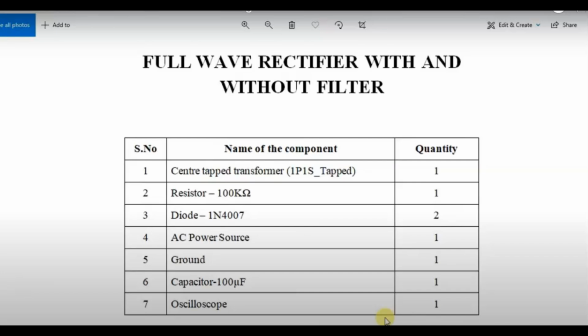The rectifier circuits give a pulsating DC, and this pulsating DC output is also called the ripple. Generally the ripple is undesirable, so it should be smoothed by using some filter. The ratio of the effective value of the AC component to the average DC value is called ripple factor.